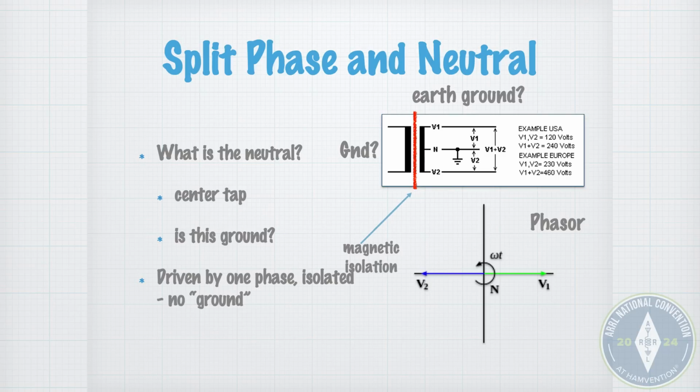And if the transformer could stand off enough voltage, you could be 1,000,000 volts away and not be referenced at all to what's up at the power lines. Then you take the center tap on that transformer and you call that neutral. And you stick that maybe in a piece of metal in the ground, whatever the code cares about. And now you have something that you're calling ground, but it's not really referenced to anything in particular.